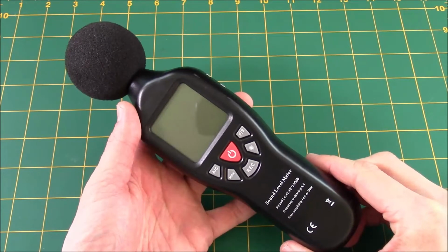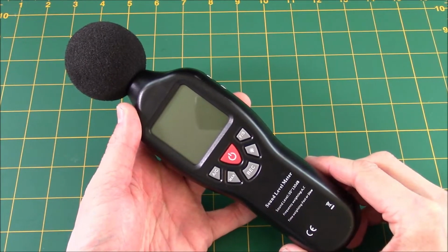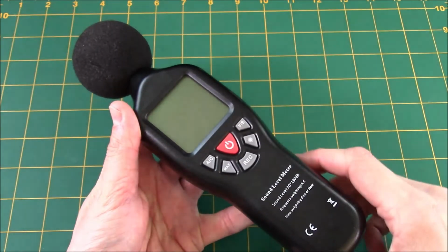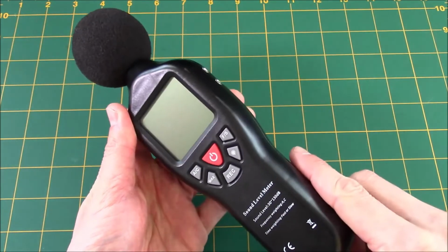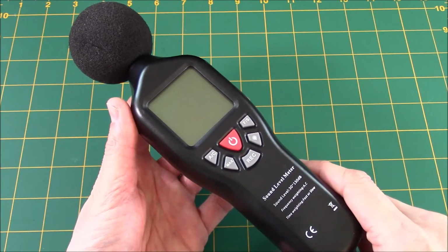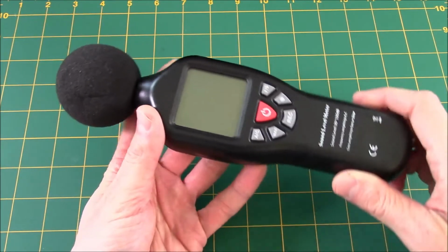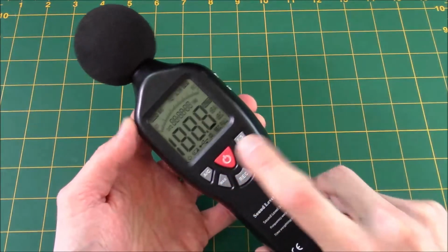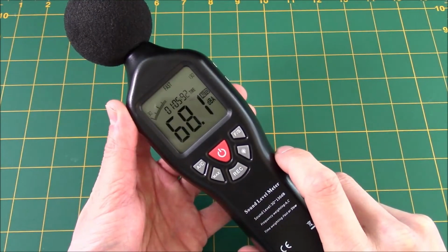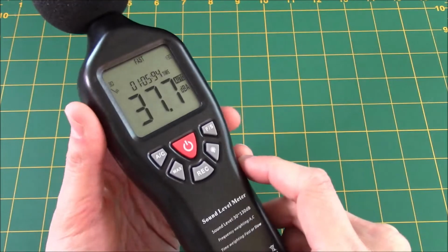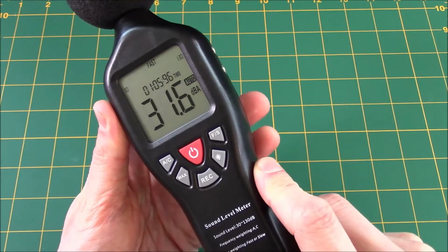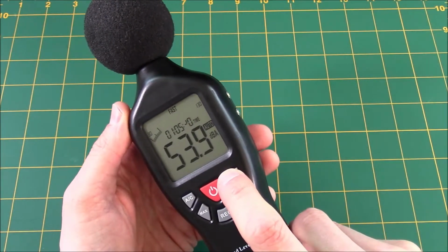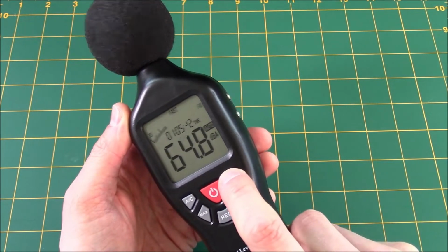Here is our sound level meter. This would be considered a survey meter, given the price and calibration of this device. Survey meters are widely available from distributors like Amazon for a low cost, for instance, less than $50. The sound level meter, when turned on, will register the overall dBA value, currently operating in a fast mode, which you see at the top, and which could be changed to slow.